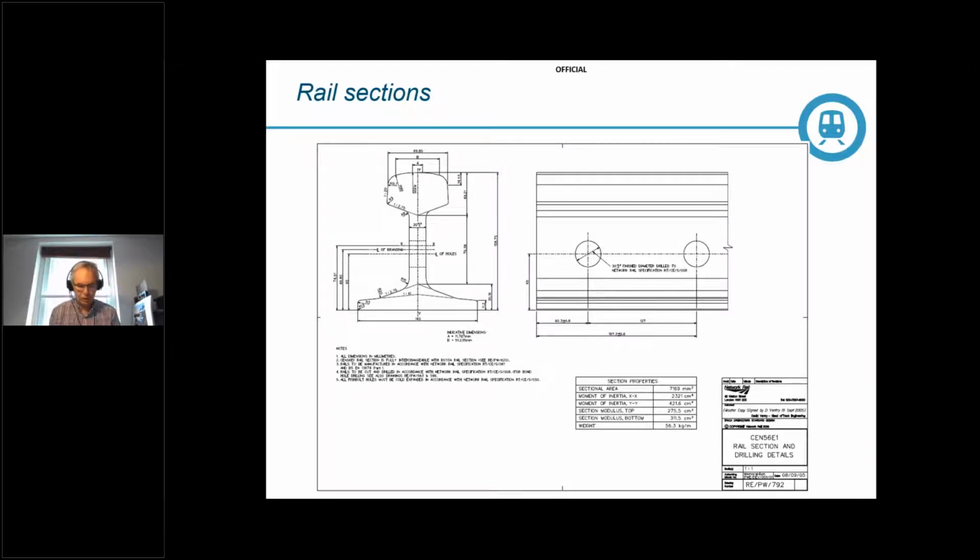Rail, however, is not like a normal structural steel element in a building, for example, which will become part of a structure and will not be exposed to rolling contact or mechanical wear. Thus, for building steels, a low-carbon mild steel can be used that is tough and easy to weld.